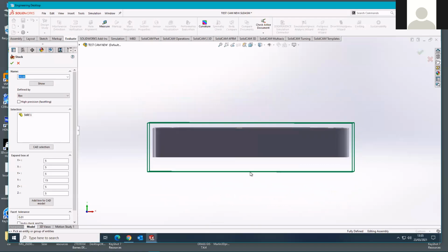So I'm giving the vise a little bit of extra material here so I can get some square vise jaws sitting on these side faces or these front and back faces without interfering with my ability to machine some of this geometry up here. So I need that extra piece of material in order to clamp the vise jaws onto.